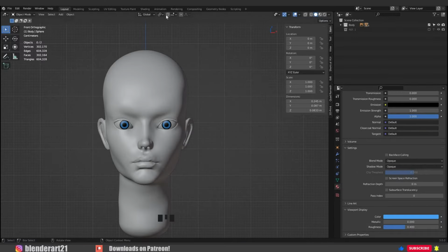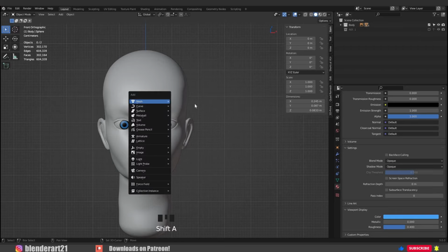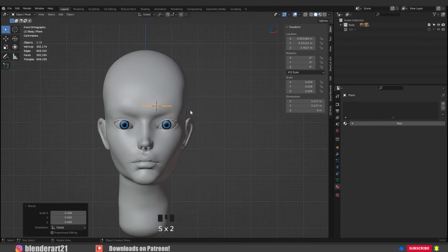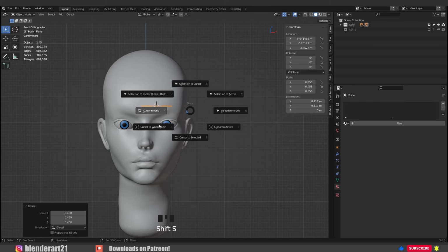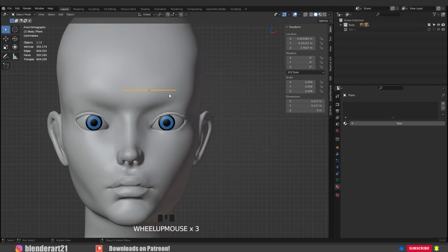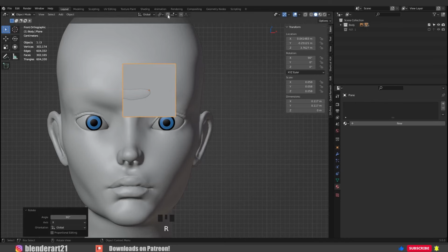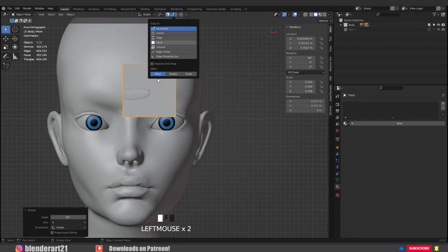To create the eyebrows, we definitely need to use snapping in Blender. Hold Shift and right click to bring the 3D cursor right there. Go with Shift A, Mesh, Plane. S to scale, and bring the 3D cursor into World Origin. R X 90 degrees to rotate around the x-axis. We need to turn on the snap icon, select face, and project individual elements.